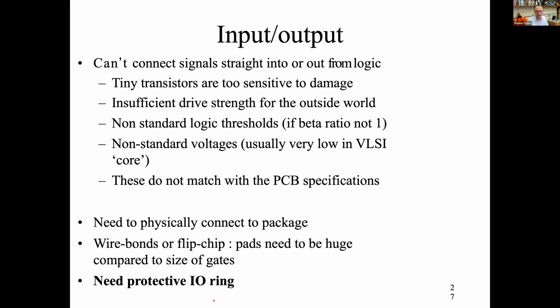They don't have standard logic thresholds, so our chip might be in a system which runs at 3 volts externally, but internally, its logic threshold would be very different. So the thresholds are different, the voltages are different, so it doesn't match with our PCB. You can't just simply connect our gate to the outside world. So what we need to do is to have some buffer in between the circuit and the PCB.